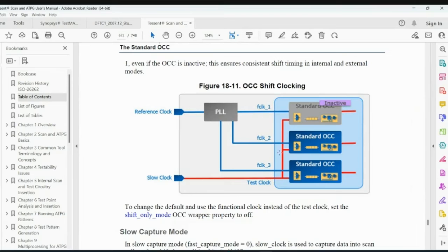Irrespective of that, you don't want a certain portion of logic to be active while you're testing another logic. That will save power. When you are testing, your agenda is to make sure power consumption is very low while you shift in, capture, and shift out.